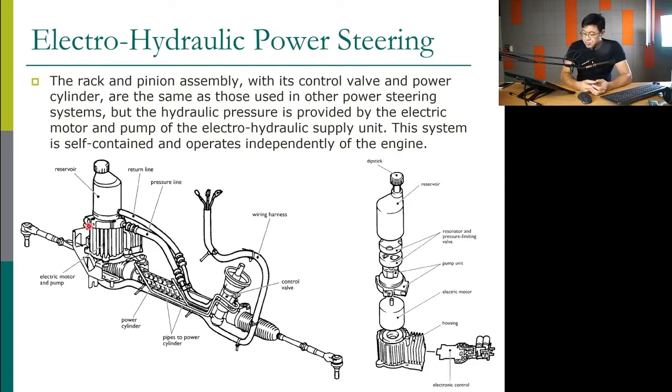Now, if we still use hydraulic, there is another problem. That problem is that hydraulic tends to leak. There are a lot of components, a lot of locations where the fluid can leak. A lot of seals, a lot of hoses, a lot of rubber. So many places can leak, even inside the cylinder, even inside the piston. There is some leak. That's a big problem. A lot of components and there's leak.